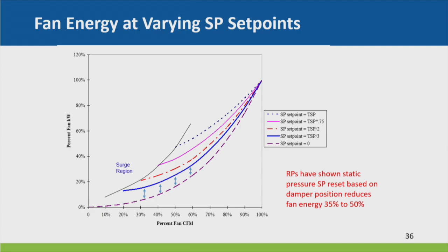And the reason for that is, doesn't the cube law not work anymore? Yeah, no, the cube law is still working, but the motor efficiency and the VFD efficiency get worse as their load goes down. And the two tend to compensate each other, and so it tends to flatten this thing out right in here. So it means that below about 20% speed, there's not much value in going slower than that from an energy perspective. But there is from a controllability perspective.